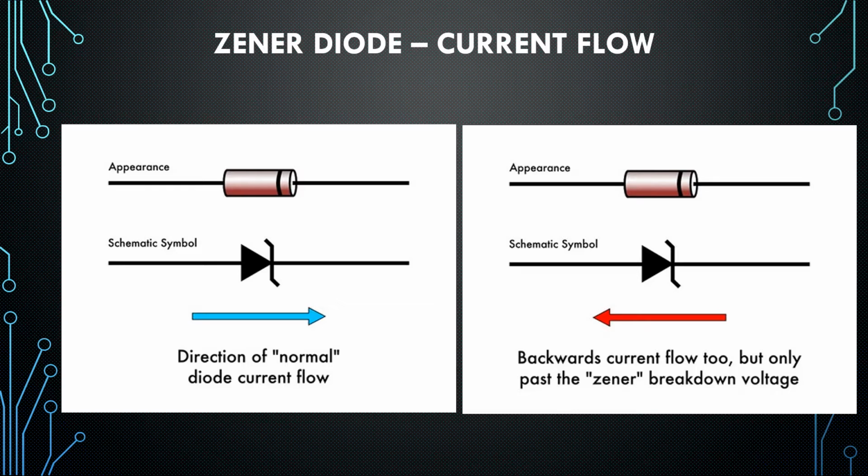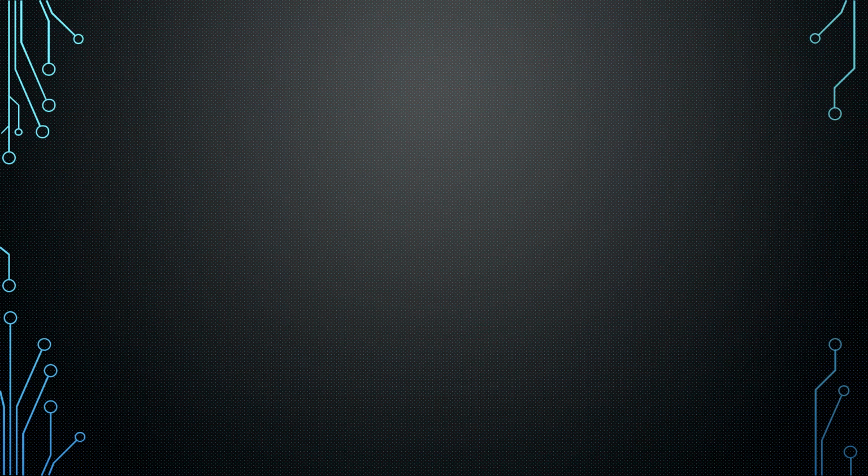This diode contains a reverse breakdown voltage for current conducting as well as continuous operation in the mode of reverse bias without getting smashed. In addition, the voltage drop at the diode will remain stable over an extensive voltage range and is one of the main characteristics which makes this diode suitable for utilizing in voltage regulation.